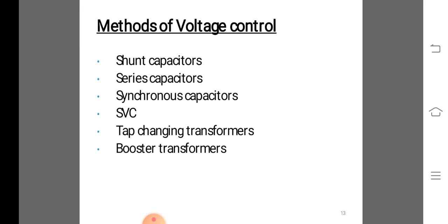If reactors are installed at line ends and intermediate substations, they can compensate up to 70% of charging power, while the remaining 30% of power at no load can be provided by the under-excited operation of the generator. With an increase in load, generator excitation may be increased with the reactors gradually cut out.